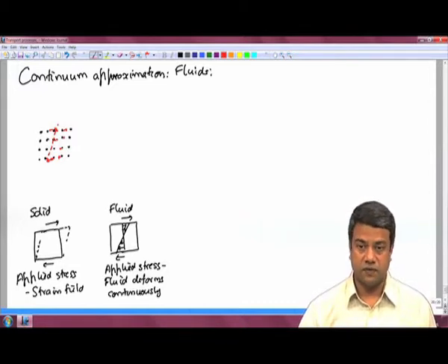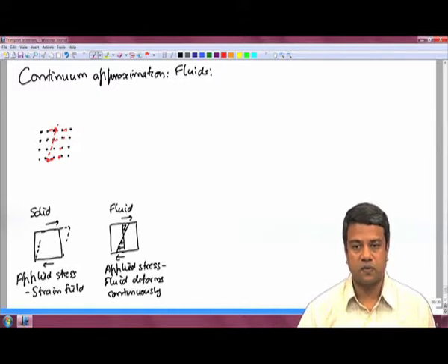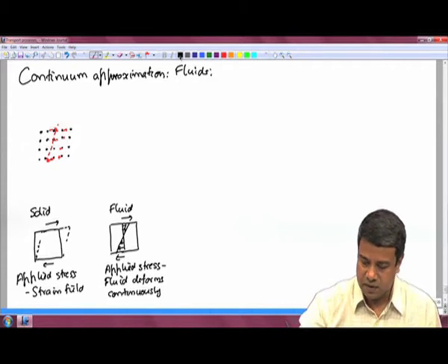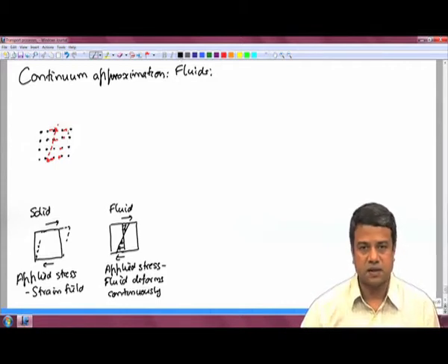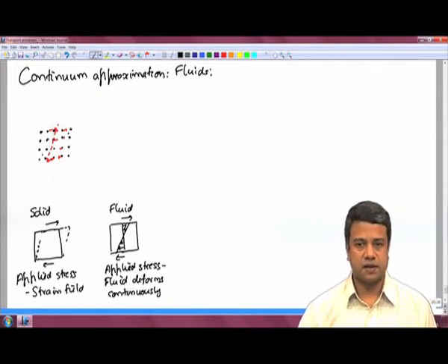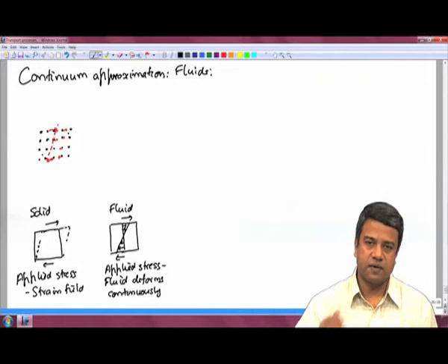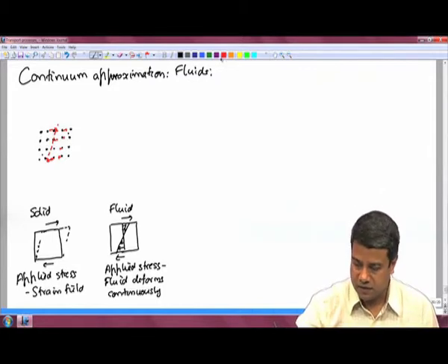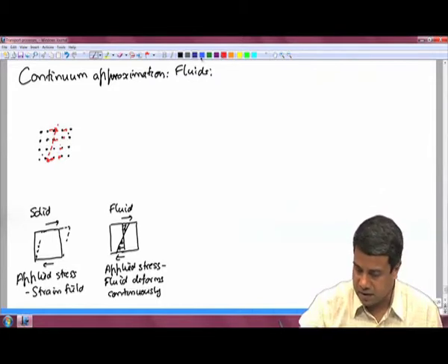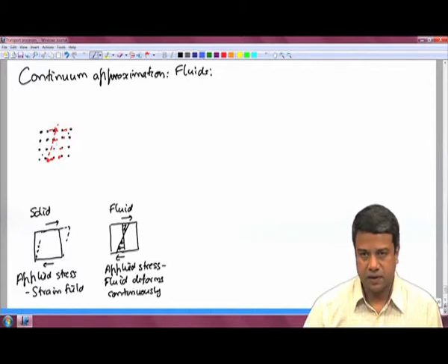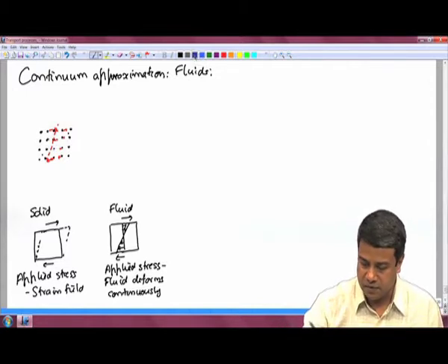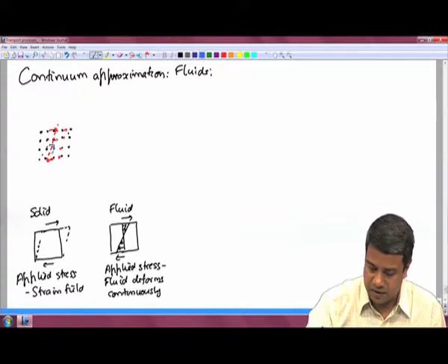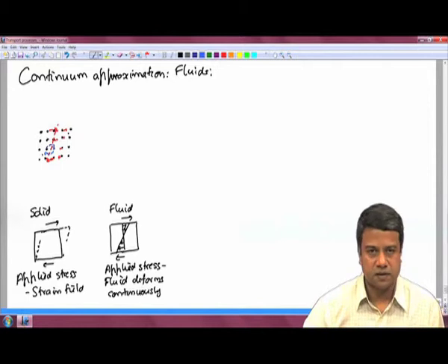There is of course diffusion in solids. It takes place by two means. One is the interstitial diffusion due to molecules which are imperfectly located within the interstitial space of the solids, and the other is due to vacancy migrations. Certain locations may not be filled with a molecule. So, if you have a vacancy within a solid at some location, you could have another molecule move in, and consequently the vacancy actually migrates the other way, in a solid.